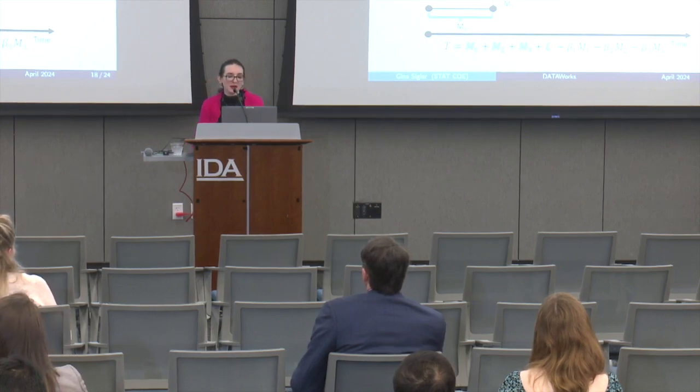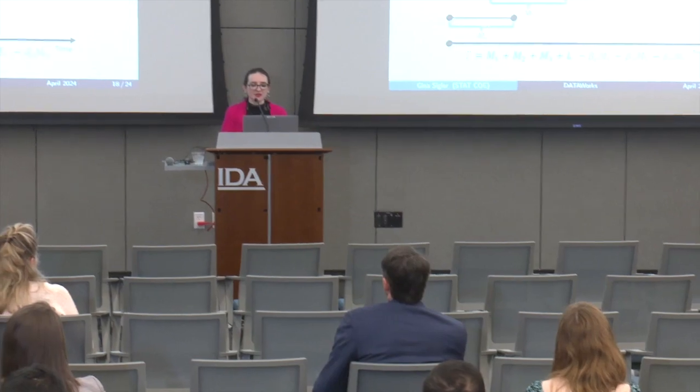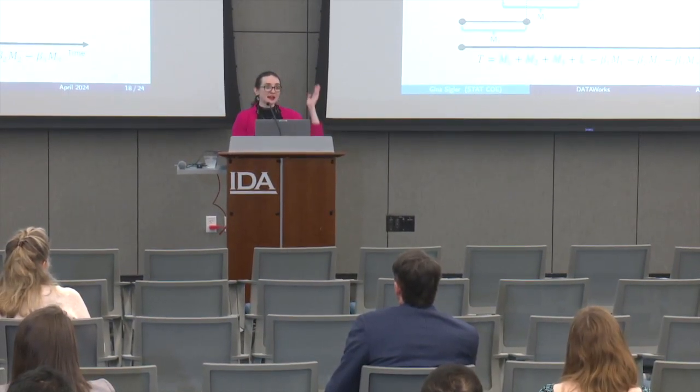Yeah, so the Weibull itself, along with the exponential, gamma, beta, you can set your time points for those. Weibull and exponential start at 0 automatically. So you can never have anything negative. It's why we don't use the normal typically for reliability calculations. But the easiest way to do this is if you're trying to fit a distribution at the beginning, if they'll give you data and you can actually calculate the time curves, you can plot it out and fit it handily enough.